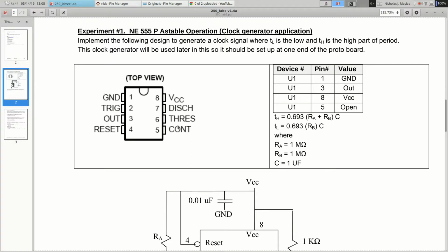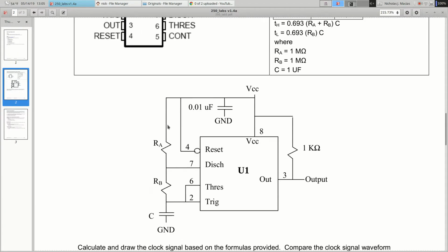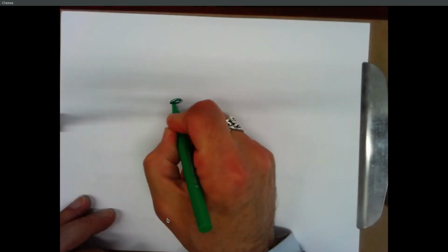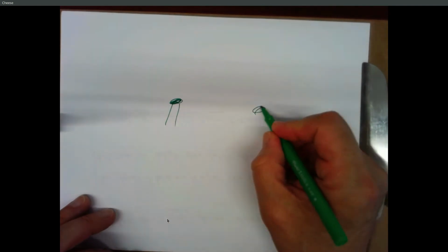We don't need to worry too much about what these other inputs mean, because we're going to get a wiring diagram for how to hook up this chip. Pins 2 and 6 get connected together. Pin 2 goes through a capacitor to ground. Capacitors are possibly a new type of component to you. They're usually little orange blobs with 2 wires coming out, smaller than resistors usually.